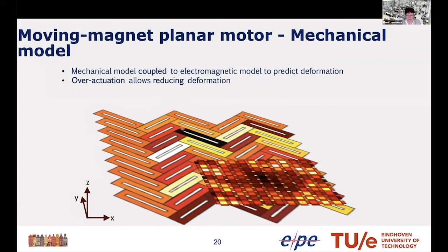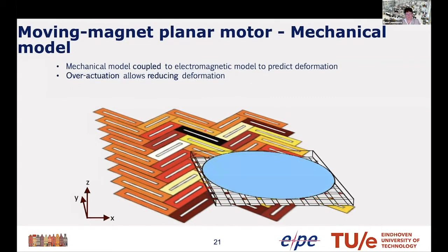So to show you how it is looking, the first example was demonstrated with the bend and mold, and compensation is coming from associated additional coils which compensate the bending. The colors which you see over here around each coil are introducing also the thermal stress. Because of the different amplitude of the current in this structure, individually fed by power amplifiers, which can of course be grouped by means of a multiplex solution to a group of coils powered by a single power amplifier, but due to the necessity to compensate the bending modes, the stresses or thermal distribution is quite different.